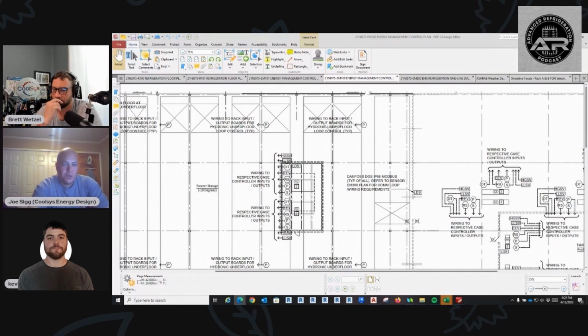When it comes to CO2 and leak detection, unless you have a drastic leak, the leak detectors are not going to pick up on a leak. It's got to be like a dump, because you got people that are walking through these spaces, they're breathing out CO2 all the time. So there's some insensitivity to CO2 inherently in the detectors. Yeah, because normal spaces have about 400 parts per million to 600 parts per million. A classroom will have like 800. Right? I'm sorry, Kevin, I cut you off. Yeah, they're extremely unreliable with that. It's got to be just absolutely blowing for it to go. It's got to be a dump.